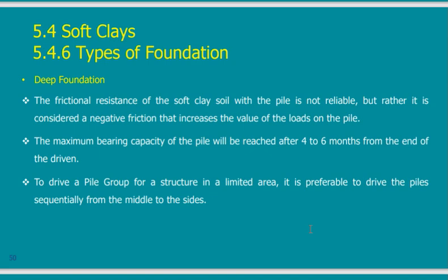In soft soil, I'm pushing my piles inside the soft soil to reach the good soil. What about the friction with this soft soil? Can I depend on it? No. So in this case, frictional forces are minimum because there will be frictional forces only in the portion of the good soil. But in the portion of the soft soil, it is zero. I don't consider it. To the contrary, it's a problem.